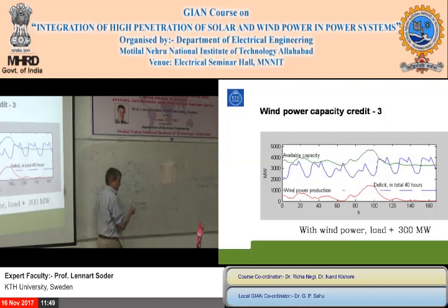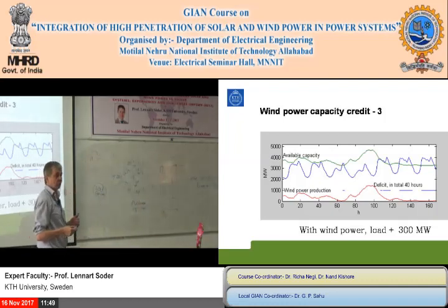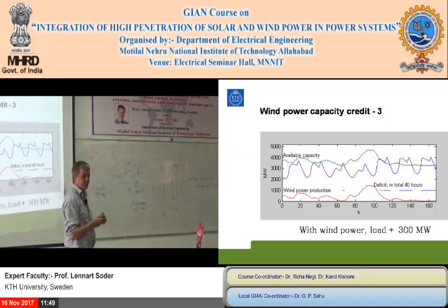This means that you first have to calculate the LOLP considering the reliability of these lines, reliability of these lines, reliability of the power plants here, how the demand is changing and so on. This starts to be very complicated. Then you are working with something called Monte Carlo methods. Has anyone worked here with Monte Carlo methods? Okay, you have worked? Because that is a challenge in itself, to get efficient Monte Carlo methods. So that is what we have worked with here.